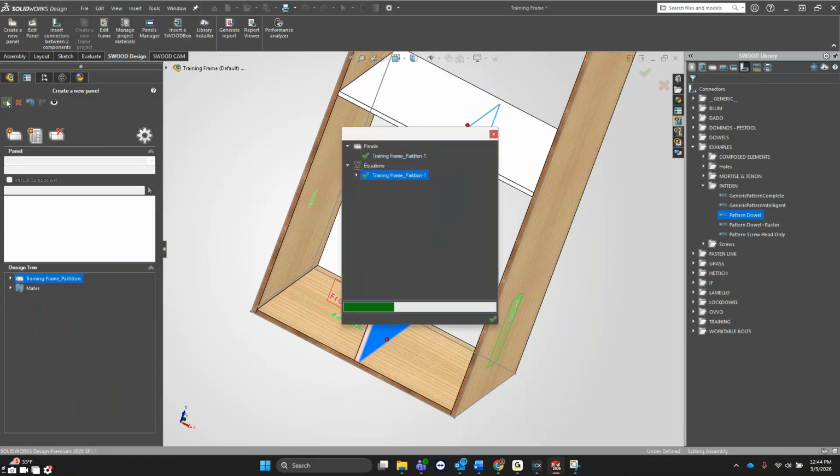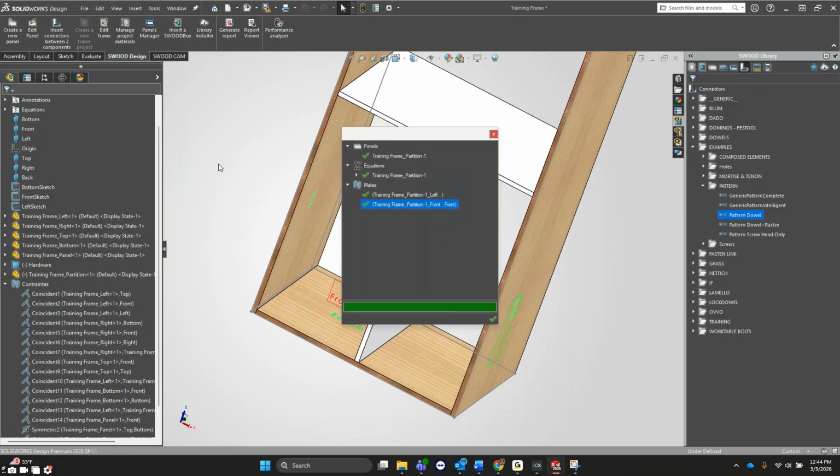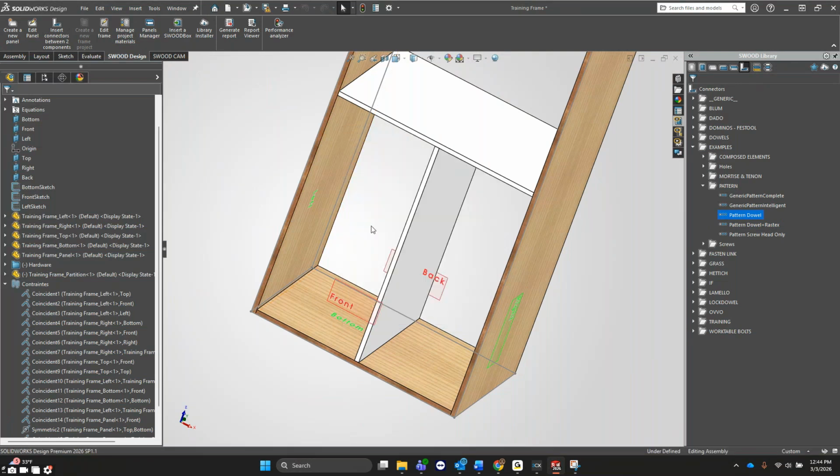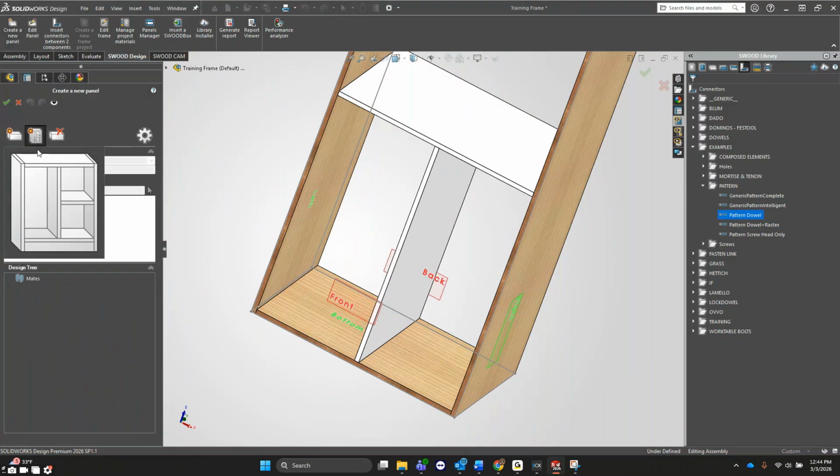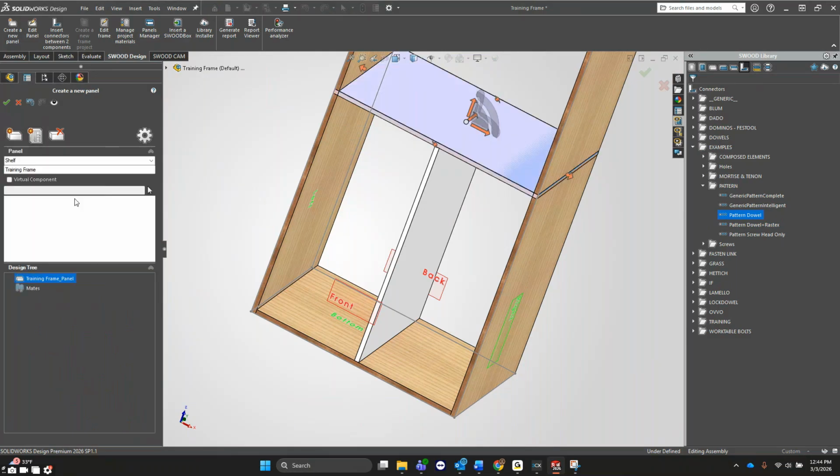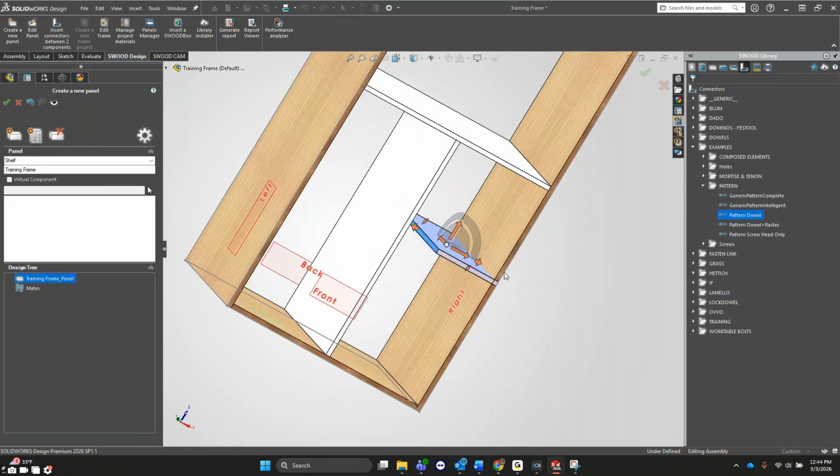Can you set the panel as the equidistant middle thing that you did before from this menu, or do you have to go to the SolidWorks mate menu? So this really only gives you access to the basic mates. So for something like that, I think you would just need to do the SolidWorks mate itself. Okay, I can try this out real quick.